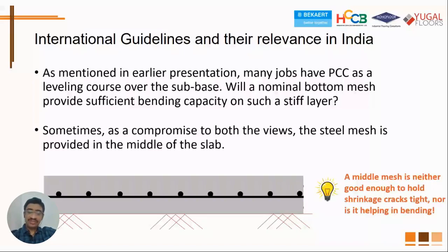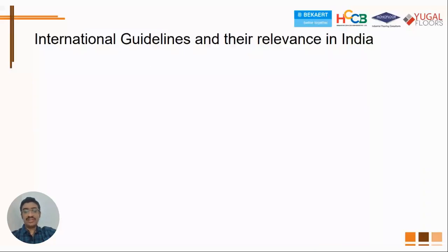The only problem is this mesh is neither good enough to hold the shrinkage cracks tight, nor is it good enough to basically help in bending. So it goes down as a waste anyhow. So these are some questions that we need to ask as designers ourselves.